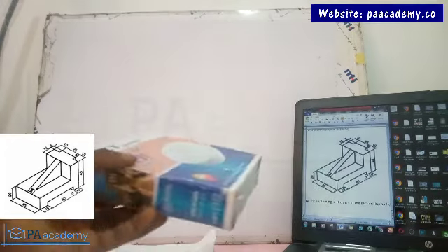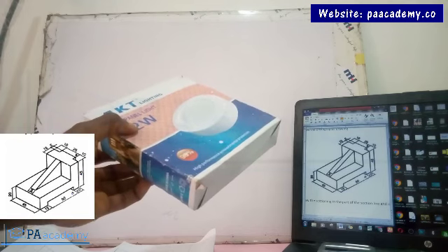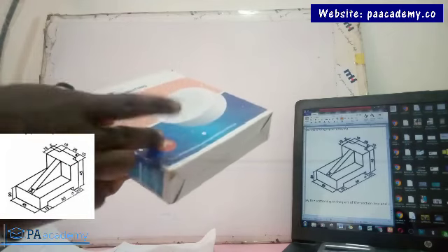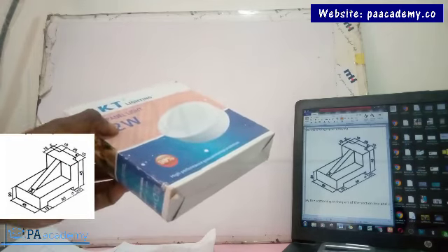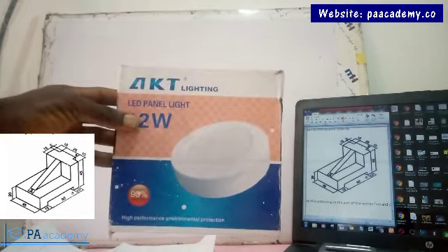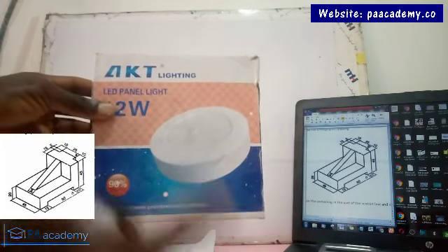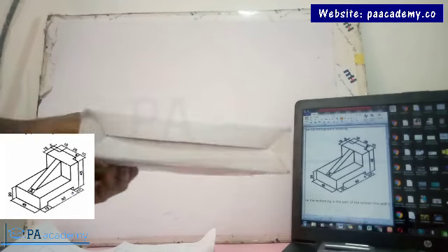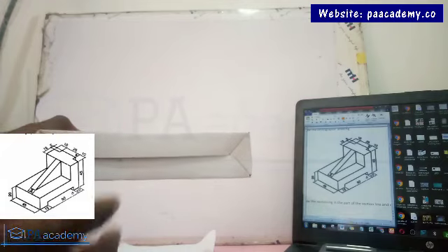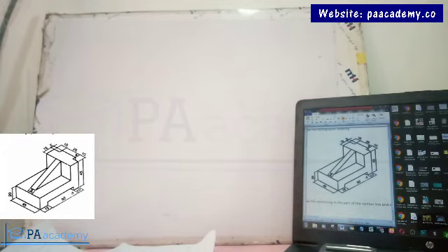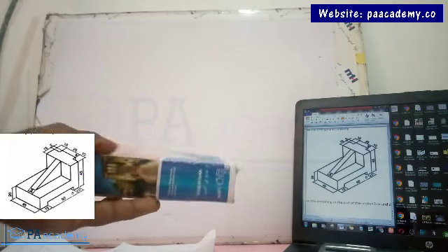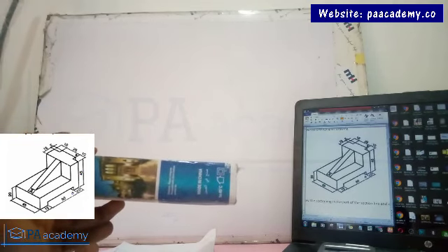Now using this box as an example, if I position it like this, it's the same way the drawing on the screen is. You can see this side, and you are seeing the top. But if I want to draw the first angle projection or the third angle, I'm going to look at it such that I'm looking at just the front like this. I can't see any other side, just the front. If I reposition it and look from this position, I'm seeing only this place. I can't see the left, the right, or the under. So that's the idea behind first angle and third angle projection. Whatever face you want to pick, you are going to look at it like you are looking at just one side of it without seeing the other part.